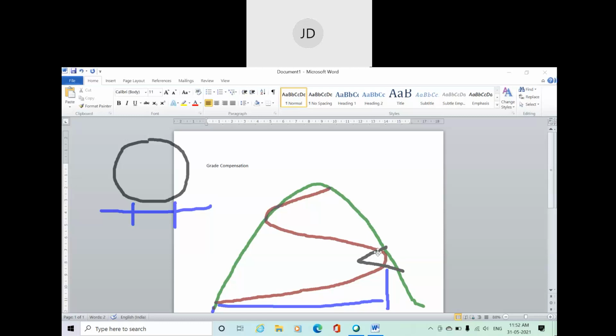If you increase the radius, the curvature will be broader. But this is not easy to provide. It involves cost and time. Another option for safe movement of the train over the curve is to reduce the gradient. We should minimize the gradient provided here, especially in the case of a curve. Reducing the gradient is called grade compensation.